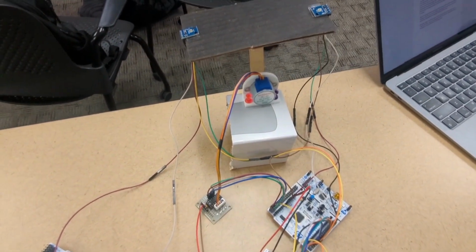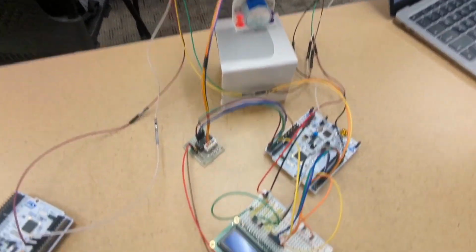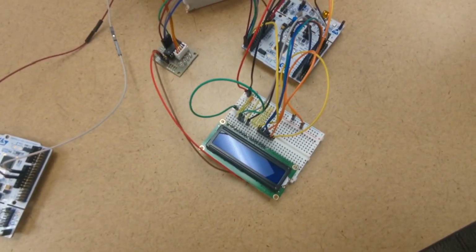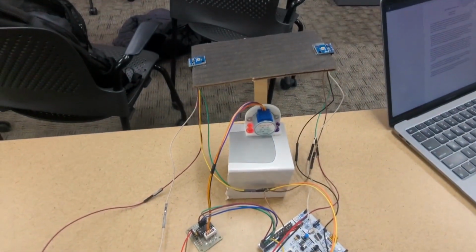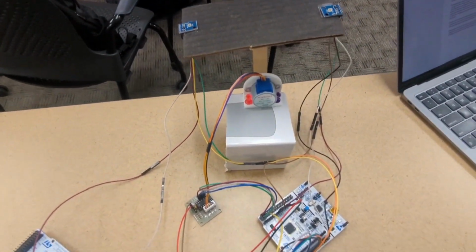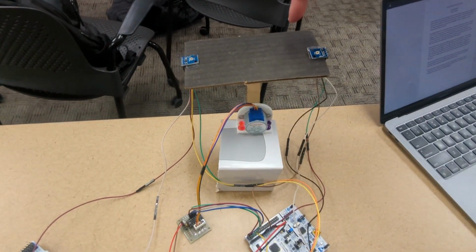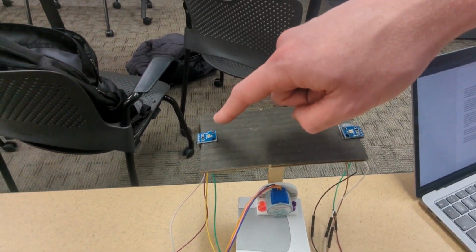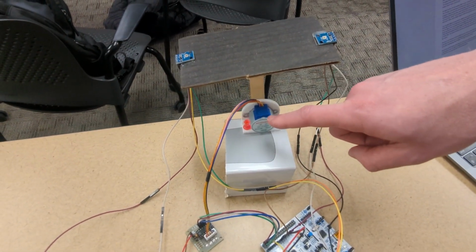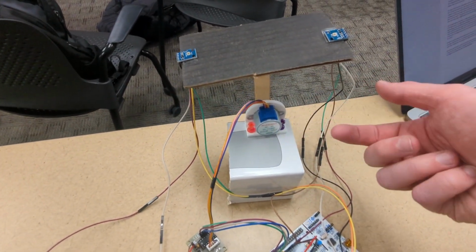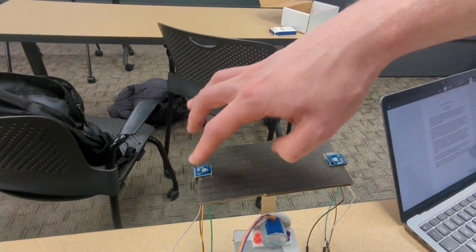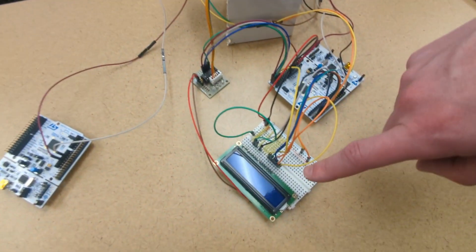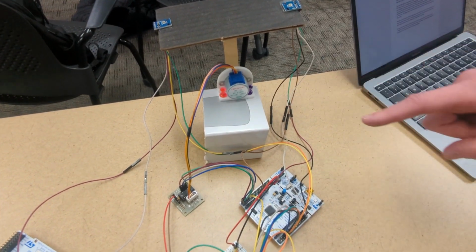Originally in our proposal and in our design, we were going to have the light sensors compare readings to move and rotate the angle of the solar panel system until both readings were the same. But just to avoid any problems with the system moving around too much, we decided to include a buffer of 1,000 lux. So, for example, if this sensor was receiving a lux value of over 1,000, then this sensor, we would activate this little stepper motor right here, and it would tilt the panel to this direction in order to bring this sensor closer to the light, and works the same with this sensor. So once we get the values from the LCD, we compare it, and then activate the motor.